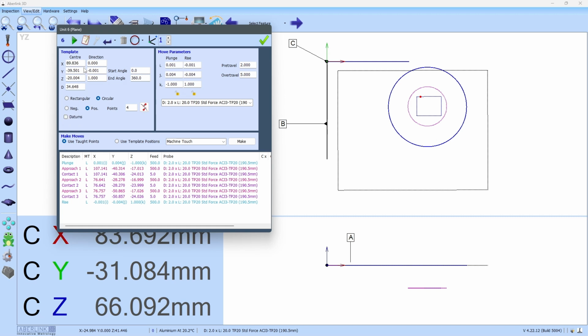So if we leave that as it is now, we've got no way to zero it out on this central bore. So if this bore and all the features with it are done in a different operation and it moves 1 millimeter to the left, when we run it, this plane will crash. So we want it to be able to zero itself out every time it measures this circle. It then knows exactly how to center these two circles.